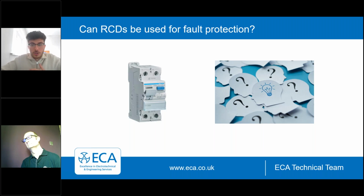And where so, the maximum disconnection times and the maximum impedance values should be verified against table 41.5 within BS 7671. Where that is the case, of course, overcurrent protection shall be provided in accordance with chapter 43.